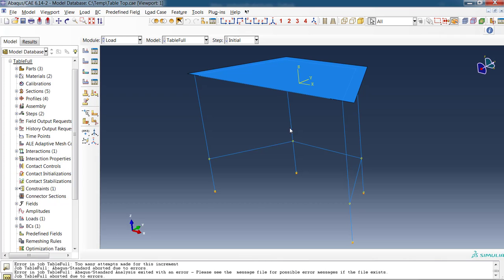What I mean by that is the uncertainty, or as I called it, the dynamic state of your system, is caused by applying a force to something that wasn't held in place. If instead of applying a force, I apply a fixed displacement, that fixed displacement keeps things from flying apart. So that's what I'm suggesting doing.